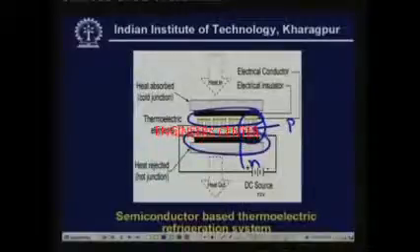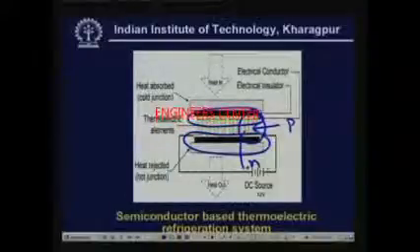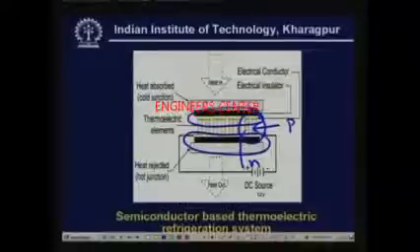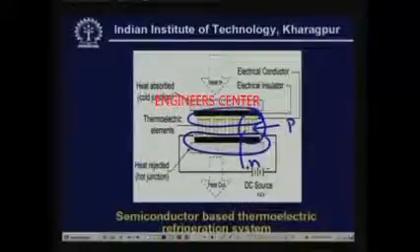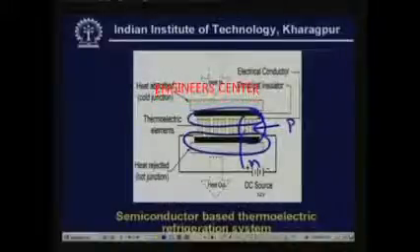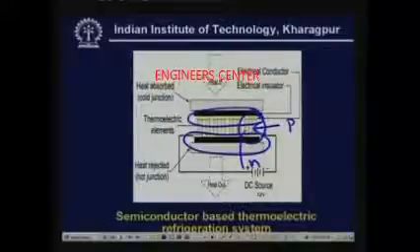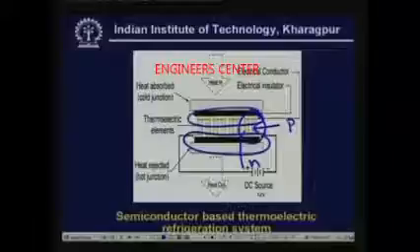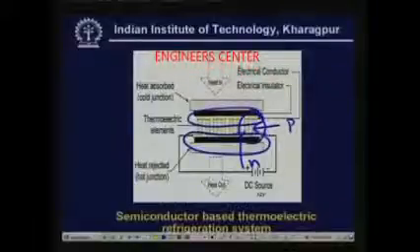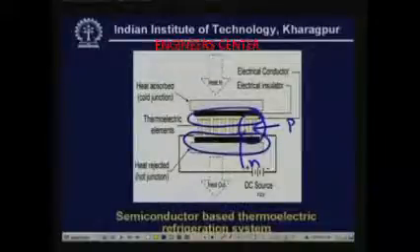Now when you connect this thermoelectric module to a DC source, let us say at 12 volts, and start giving the power supply, electrons will flow through the P and N elements and through the thermoelectric module. And as I mentioned, as electrons flow from P to N, they produce a cooling effect. So you have cooling on this side. Okay, and when it flows from N to P, you get a heating effect. So you can see that this junction is hot. So by designing them in this manner and by stacking them together, you get cooling on one side and heating on the other side. Okay.